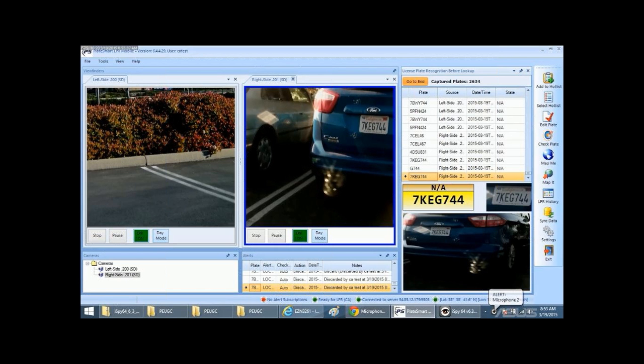So most license plate cameras at night are high contrast or black and white cameras and have special infrared that is designed to reflect off of license plates and come back to the camera. And once again, I'm going to put a little side note there and make you realize that that is the most important part. The license plate has to be reflective. If it's not a reflective plate, the IR will not bounce back into the camera, and you won't be able to see the subject. But going back, can you use an IP camera? Yes, you can. During the day, it will work.